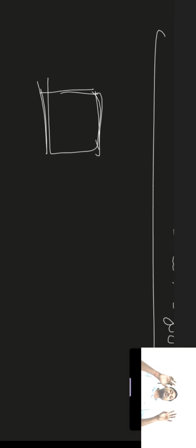Holes within the same prescribed upper and lower limits will be used to obtain a clearance fit, may be used to obtain an interference fit, or may be used to obtain a transition fit. So this type is known as the hole basis system.